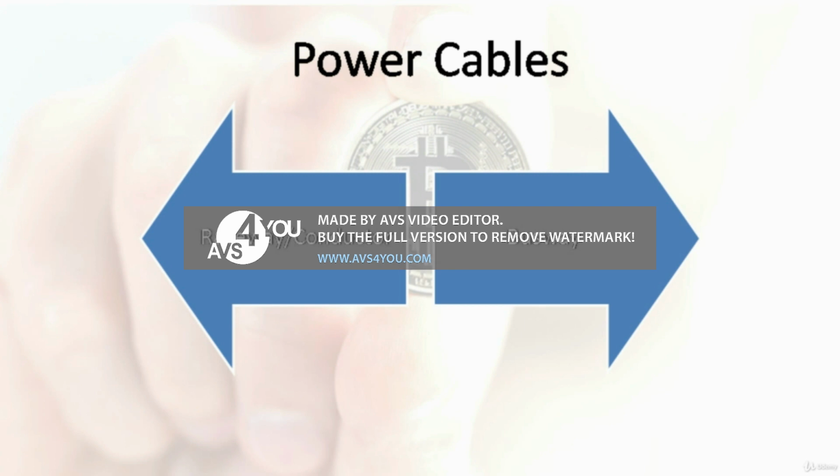The raceway conductor method utilizes conduits or tubing with insulated phase, neutral, and ground conductors, where each raceway and conductor is field fabricated. The advantage of using raceways is that changes can be made comparatively easily, but it is limited to the number of bends before you need a junction or a pull box.